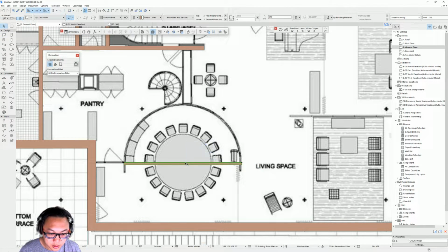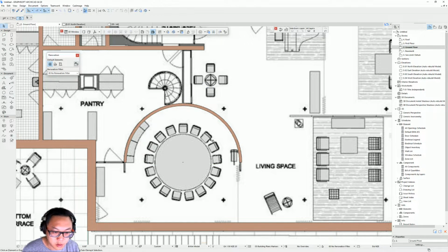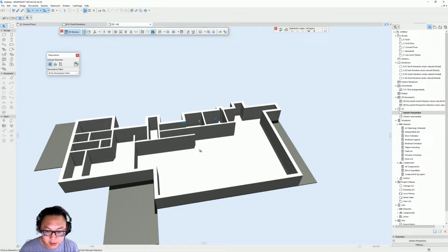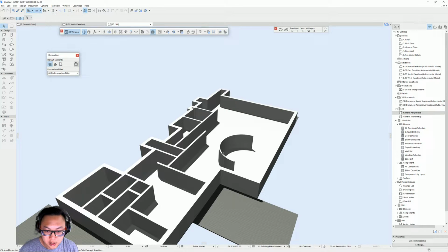And now if you take the center here, or maybe just the edge, just like the slab tool, you get some options to edit that wall. And we're gonna use the curve edges. Click on that, and it allows you to create a curved wall. And 350 is about alright. You can either type it again just to make sure that it doesn't move, or just press enter. So now you get a curved wall. Go to 3D view, and that's it. Well, it's really easy.